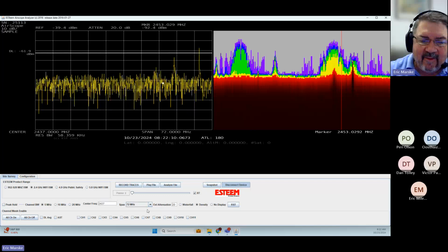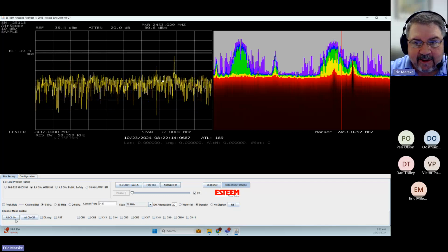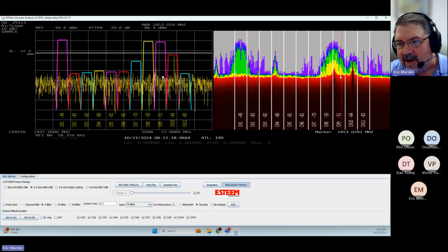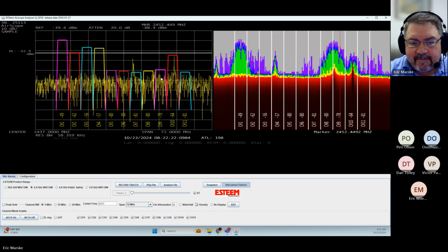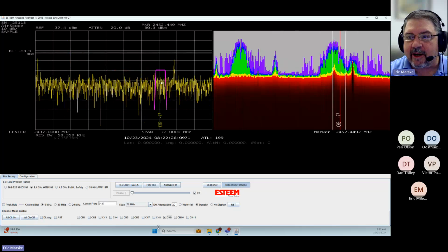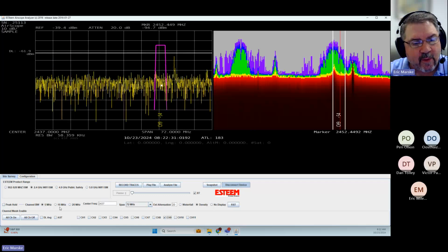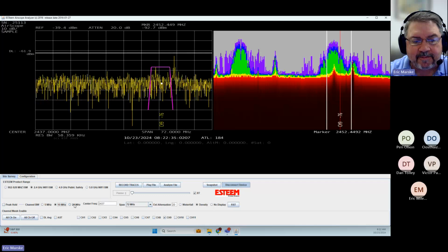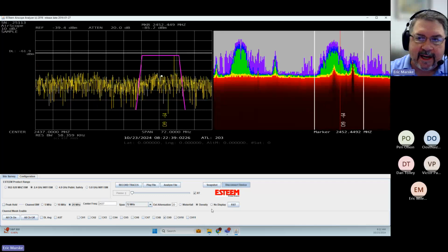What does that really mean? Well, if we see it on channels, we can actually put all the channels on. It will say, okay, it's centered around this channel number 9. All right, so that looks good. I'm going to turn them all off, turn my channel marker to channel number 9, and we can see here it's much wider than this 5 megahertz wide. Is it 10? Nope, it falls outside of that band too. It's probably a 20 megahertz wide transmitter, which we know it is.